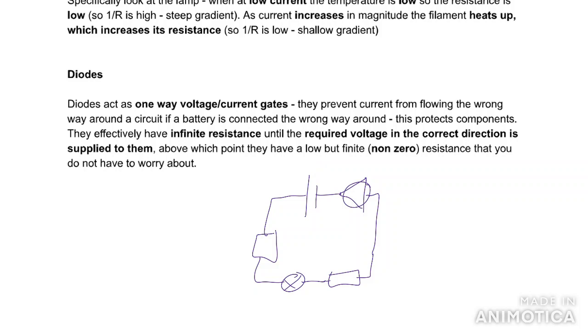So let's say we've got a very low voltage battery, we've got 0.3. Well, what's going to happen? The electrons aren't going to be allowed to travel along the road. And unfortunately, the diode is going to take all of their money. That's the voltage through the diode, which leaves nothing for the rest of them. Whereas, assuming you have got enough energy, then regardless of where the diode is, even though it's at the end here, it's still going to take its toll of 0.6 volts or thereabouts.